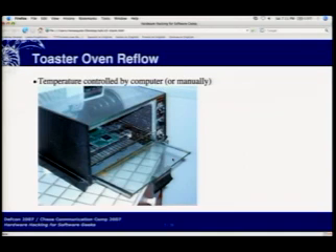They usually ramp up, hold steady to melt the solder, peak to melt anything that had a very big pad that it was being soldered to or had a very large piece of metal, and then drop off quickly to cool everything in place before any vibration knocks any parts loose. You could also just do this by twiddling the thing. I'm led to believe it is not terribly precise.